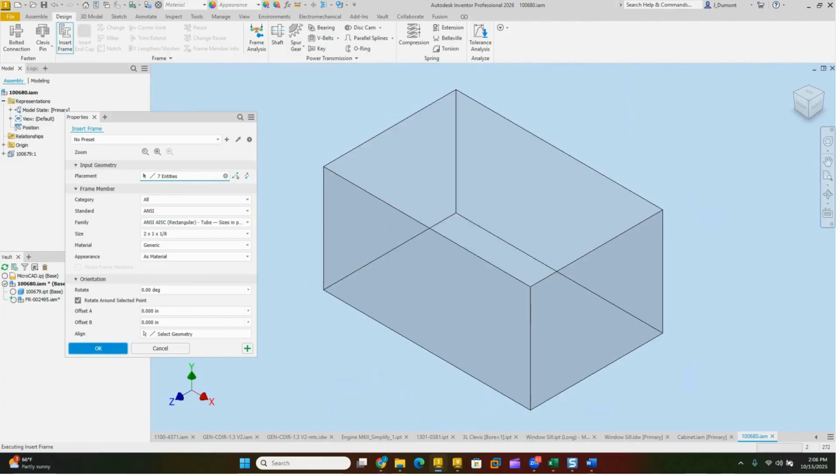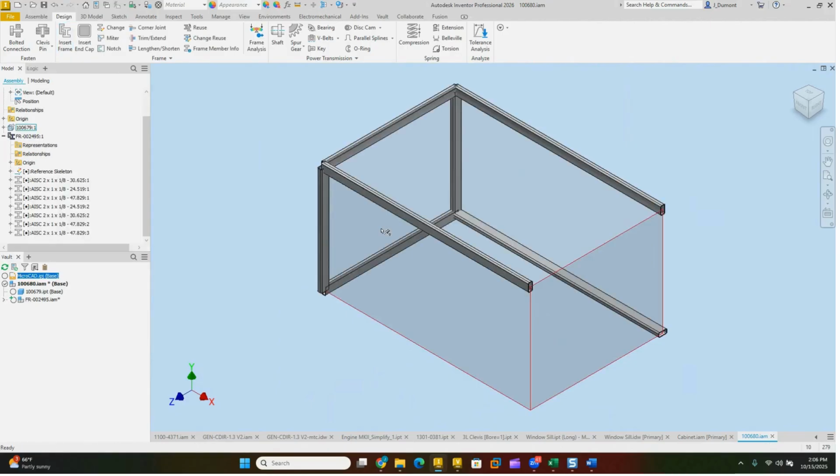So all the files get named with an FR dash. Vault is distributing those file names for me. I don't really care what they are because I have access to them graphically. I can see what they are. I can make my changes as necessary. I have full access. If you run into a situation with Vault Basic and you do create files of the same name, you can't check them in because you have it on, you could always shut that switch off.